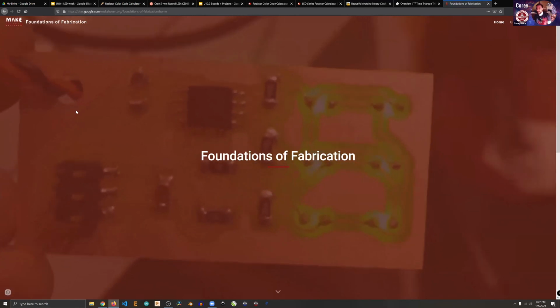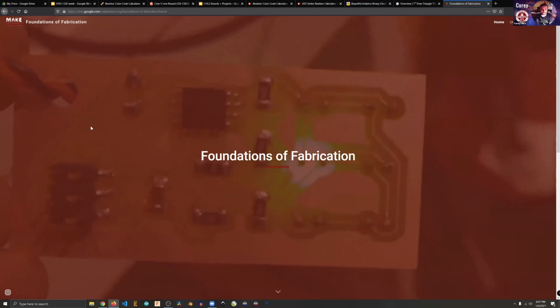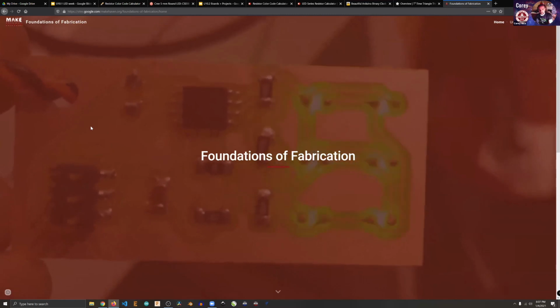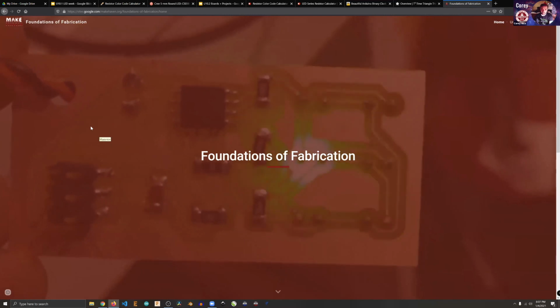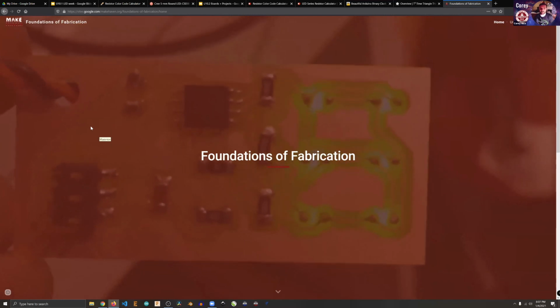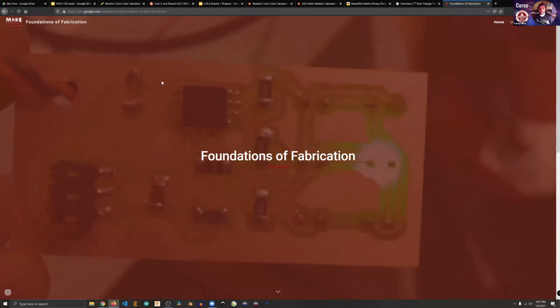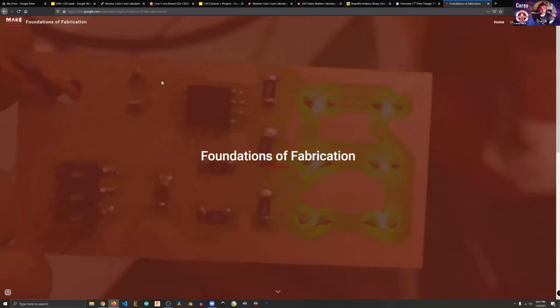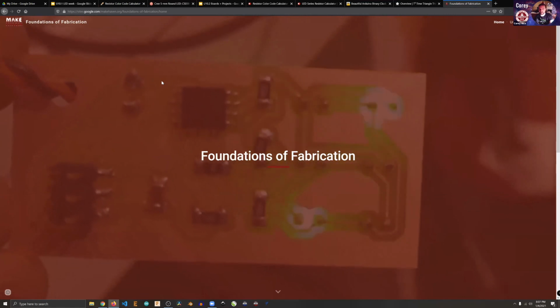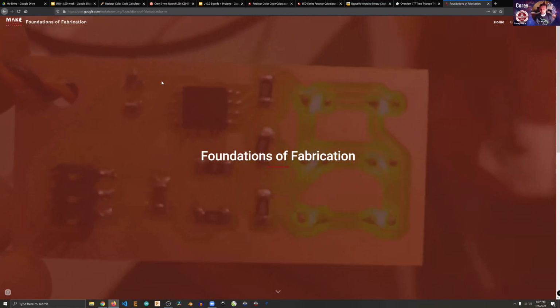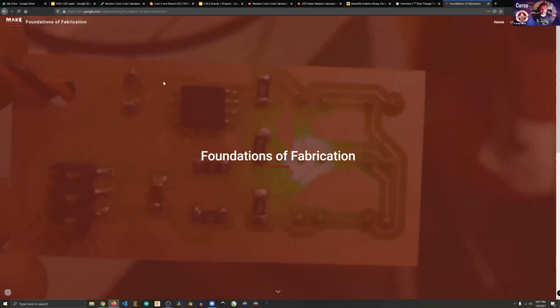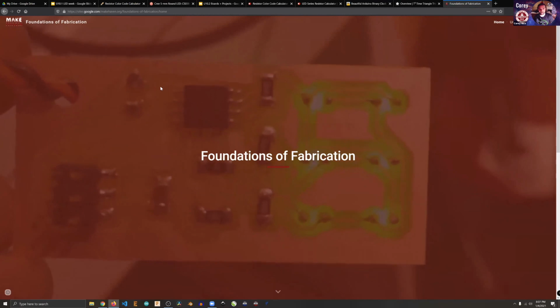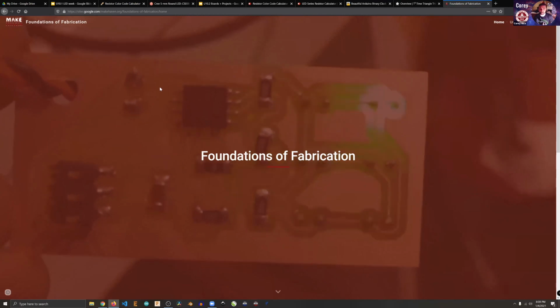So it's basically like multiplying the capacity of your Arduino by just duplicating pins, sort of. You send it commands over SPI and then it reuses those commands on the pins that it has by dealing with each byte that it gets bit by bit. So it's a shift register. It's an interesting little chip, and you can actually read the annoyingly long data sheet for all of the logistics, but it manages the power and the code, the logic for you all in one shot. So they're helpful little chips.